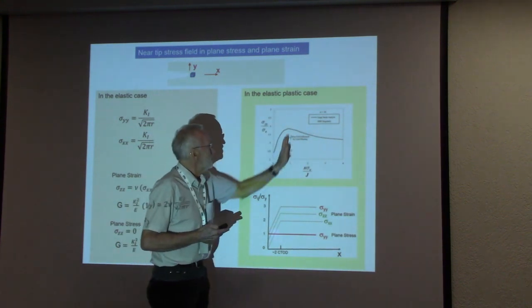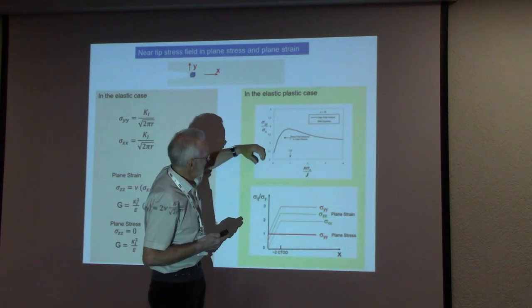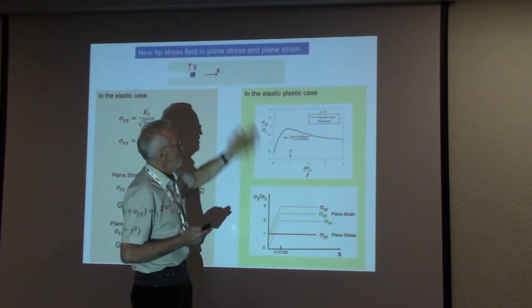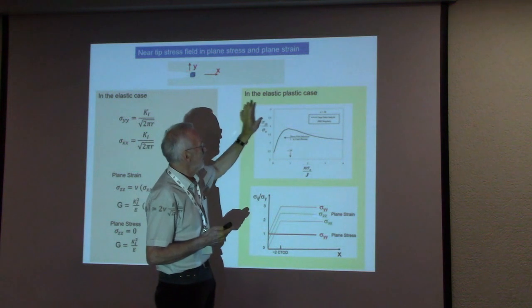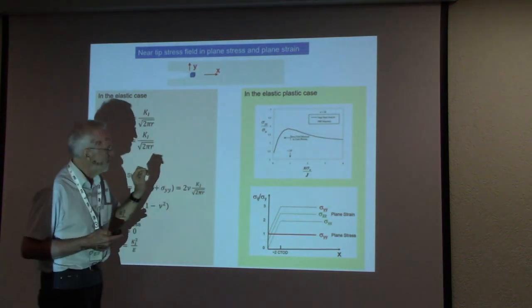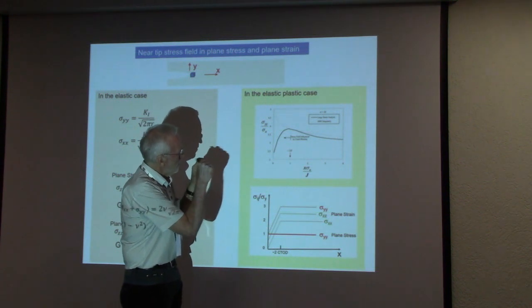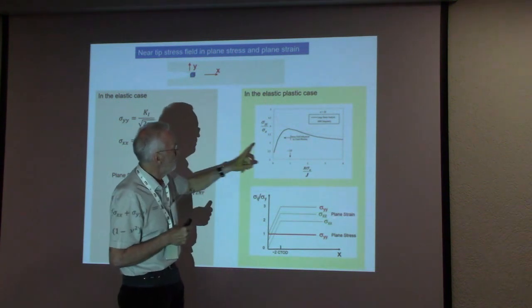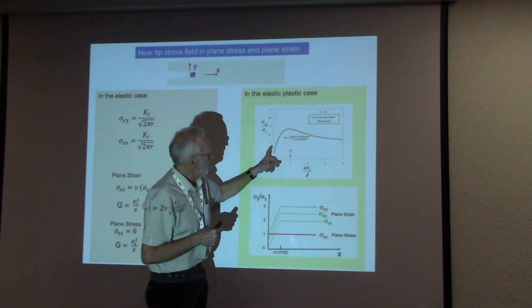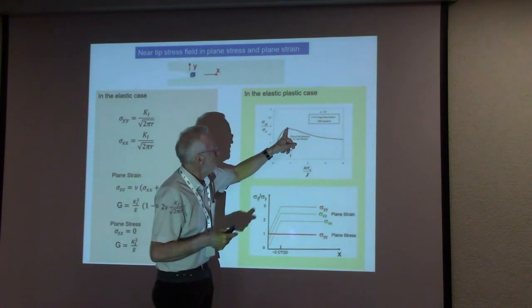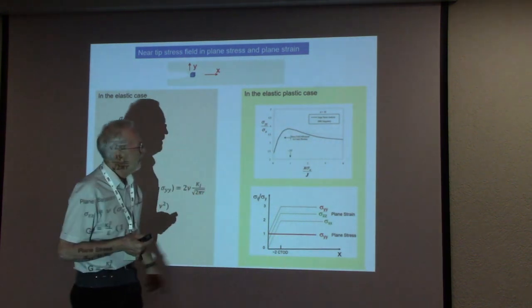This is the region of the size of the plastic zone. The HRR solution does not really describe the stresses at distances which are equal to the size of the crack tip opening displacement. But at larger distances, it describes quite well.